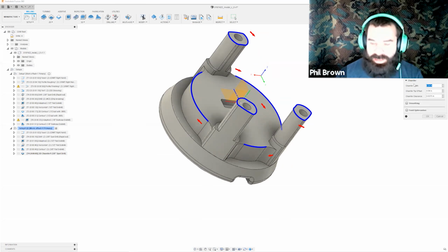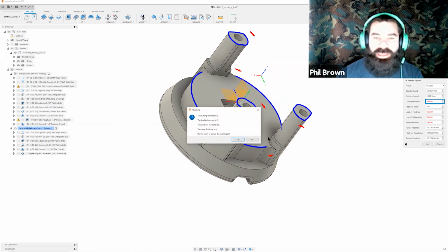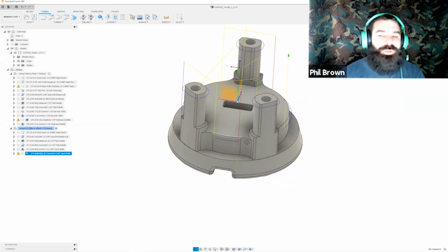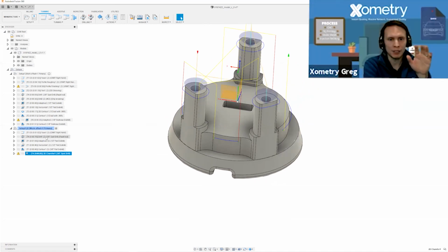So let's give everything a 10 thou chamfer to save us time. In this case, I don't have a speed tied to this tool currently. However, it will still give me that toolpath for machining purposes. And I'm a huge fan. I think everybody who gets parts is a huge fan of machine deburr. It's just so much of a consistent experience.